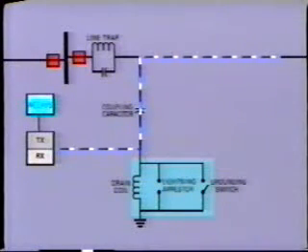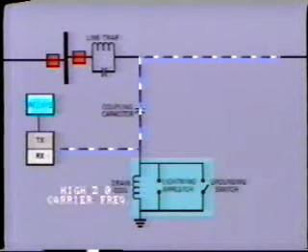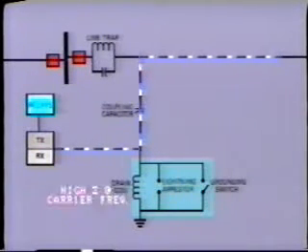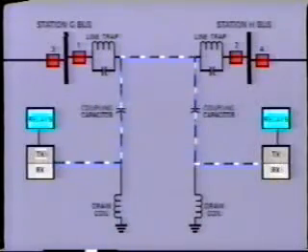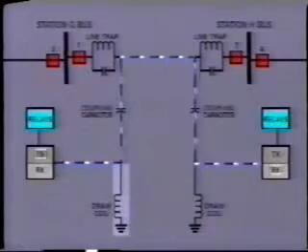The high-frequency carrier signal is connected to the ungrounded side of the drain coil. This signal will pass easily through the capacitor to the transmission line, but it will be isolated from ground by the high impedance at carrier frequency of the drain coil. In essence, the transmitter voltage signal is applied across the coil between the line and ground.